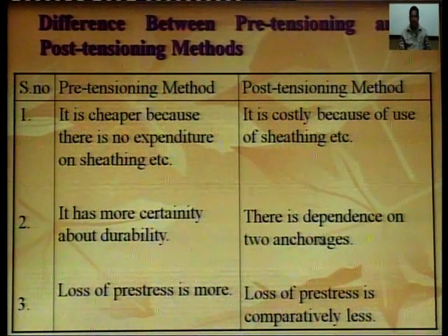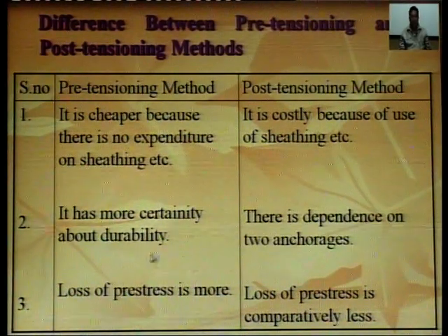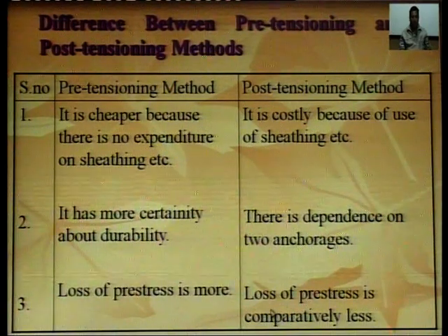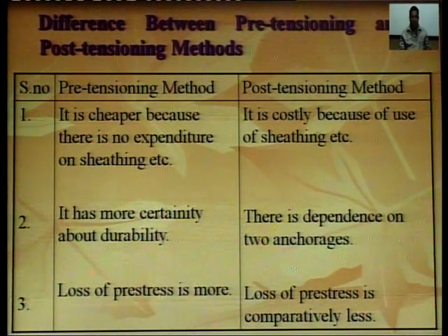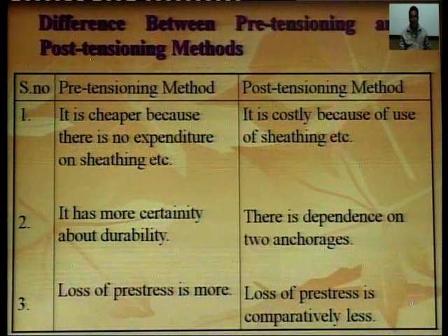There is a dependence on the two anchorages. In pre-tensioning, loss of pre-stress is more. In post-tensioning, loss of pre-stress is comparatively less than in the pre-tensioning method.